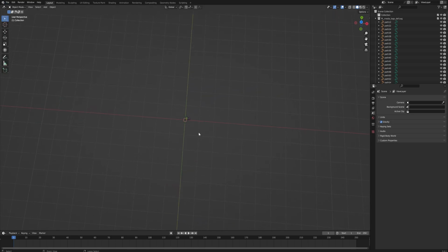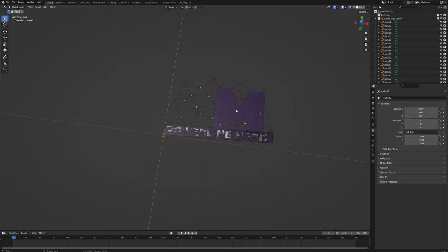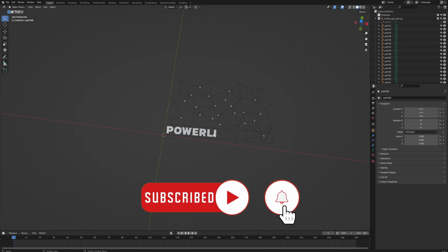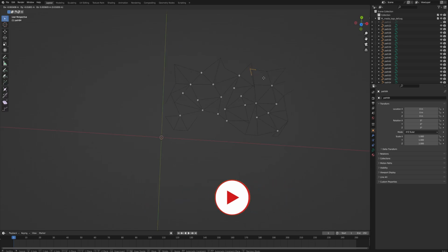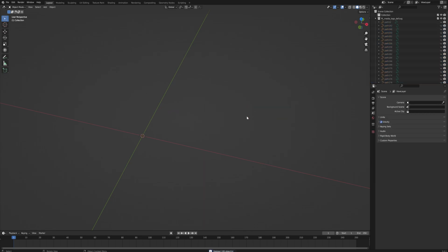And once you import it, you will see a very small scale version of your image. In this case, the vector is built up a little weirdly because, as you can see, the logo has all of these lines and these dots, which is all vectors. And I don't actually want that in my final 3D version because they're quite messy. So what I'll do is I will select everything that I want to keep, so like this, and press H on them to hide them. Now we can see all of these other vectors and how messy they really are. For a 2D logo, that doesn't matter, but for a 3D model, this is way too much trouble to really be worrying about, so I'm just going to select all of this and throw them away.